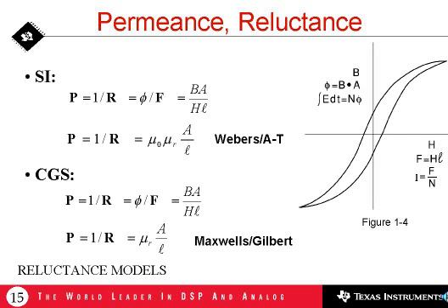There is, however, a relationship between a magnetic circuit and an equivalent electrical circuit. And this is done through a process of duality. And again, that process is described in this paper that we mentioned earlier, deriving the equivalent electrical circuit from the magnetic device physical properties, in the back of the Magnetic Design Handbook.